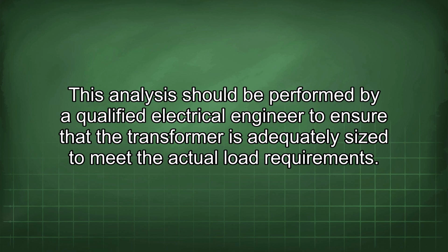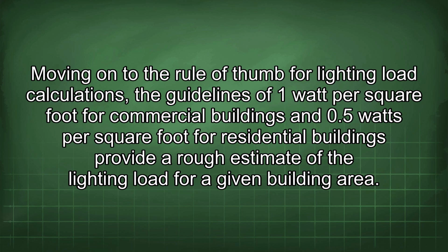the actual load requirements. Moving on to the rule of thumb for lighting load calculations, the guidelines of 1 watt per square foot for commercial buildings and 0.5 watts per square foot for residential buildings provide a rough estimate of the lighting load for a given building area.